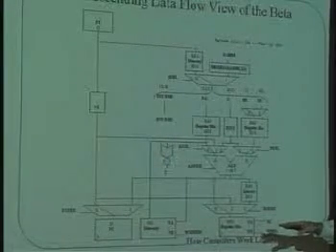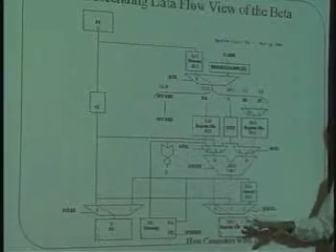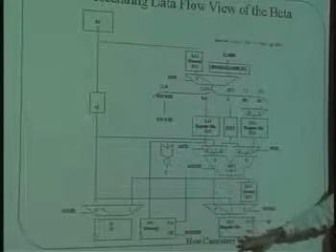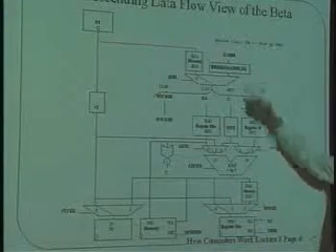And the three clocks on the bottom line go off at the same time? Simultaneously. So it's like a drum. It goes bang, bang, bang. And it's the same clock for all three of them. Every time the clocks go off, whichever writes are turned on happen. And then the new data percolates back through this thing. And if we've left enough time for it to get through, which we're going to talk about how to make sure that we do, then it's ready for the clock to go off again. Bang. Time for the next one. And it percolates through again. Bang. Time for the next one.